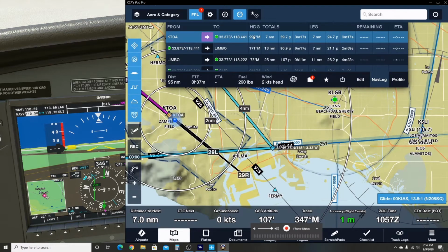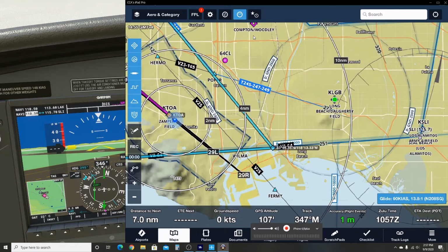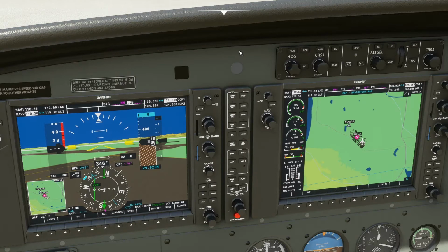I'm not sure the wind is exactly the same here in Flight Simulator 2020. It's not been very good with winds yet. So I'm gonna select heading 295 for now. And altitude initial climb, remember it was to 3,000 feet. So there we go. Heading 295, climbing to 3,000 feet to intercept the 170 radial from LAX on the VOR number 1. So that is set.